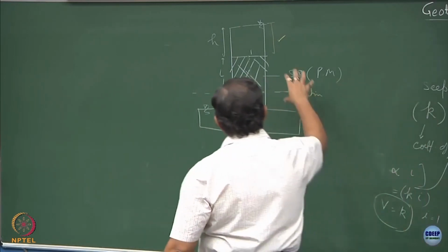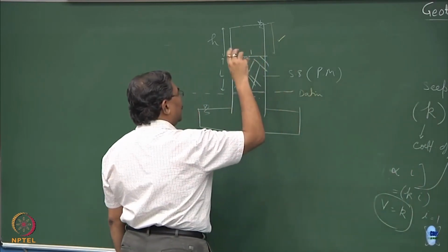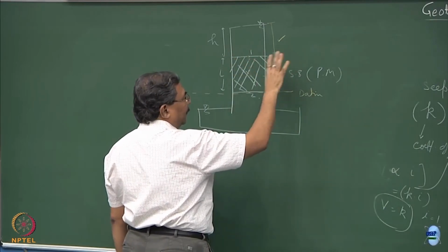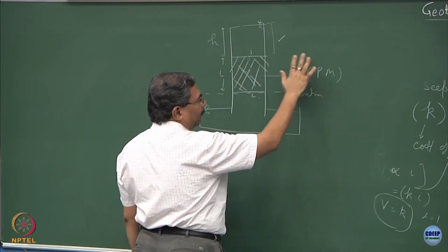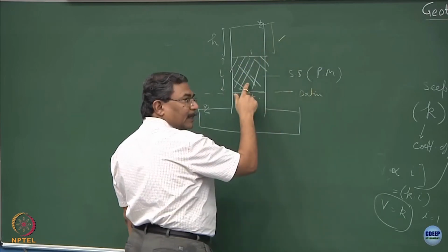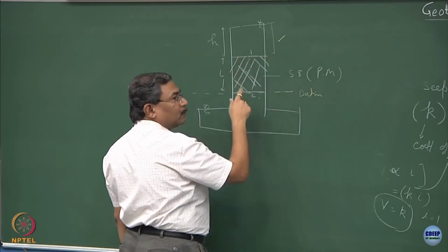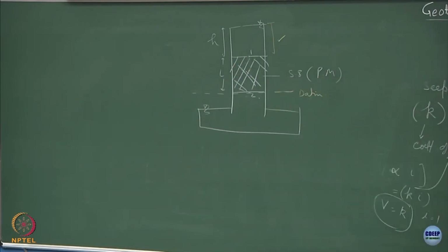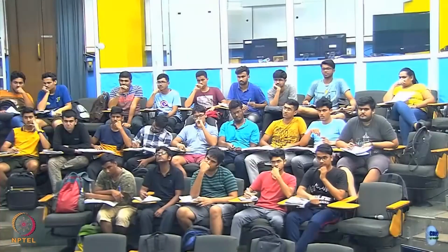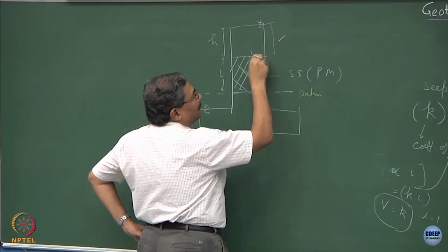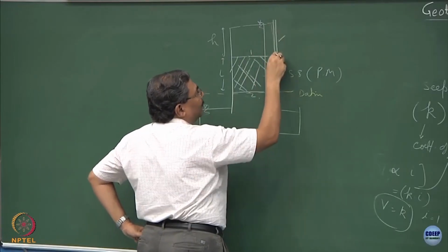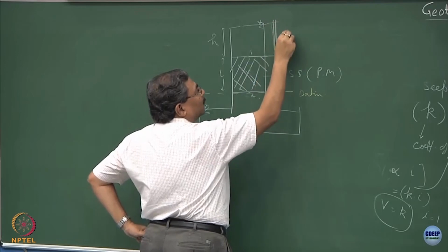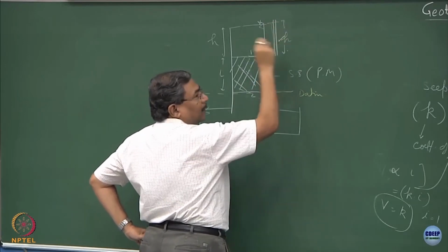By virtue of being a porous media, the void ratio, density, soil property, specific gravity all are defined. What you are ensuring is this is a steady state and hence the sample is fully saturated. If the sample is not saturated, then the problems will occur. We always talk in terms of meters of the pressure head. If you remember, the pressure head at this point is the height of the piezometric rise in water. So, this is going to be H, clear.